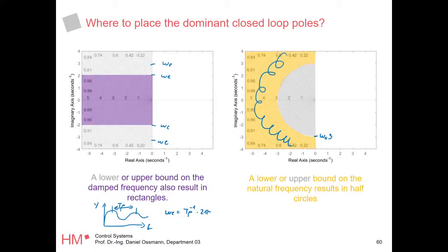So here really is where your engineering knowledge comes into play. You say, okay, my spring mass damper, or my damper in, let's say, a car, is too lightly damped, so you increase the damping. Or it's too slow, so you need to increase the eigenfrequency, or it's too fast, so you decrease it. This is how you would tackle such problems, thinking of damping, eigenfrequency, and decay time. That's basically it. And always keep stability in mind. Stability is really the key.